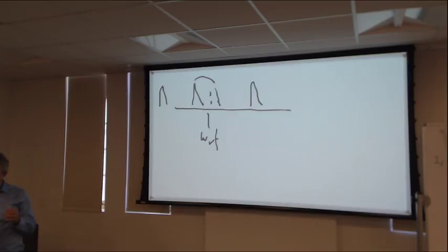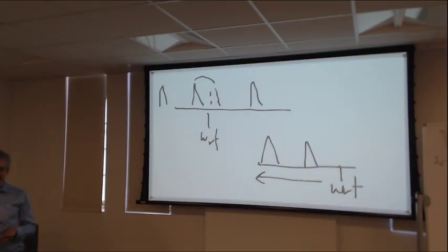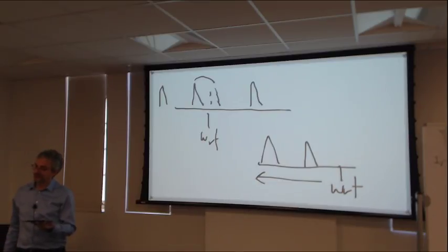The other fix, of course, could have been, suppose here's our spectrum. Let's put the frequency here, so that we only have positive frequencies. After the Fourier transform, we'll have positive and negative frequencies, but we only have positive frequencies in our spectrum, so we just throw away everything less than 0.